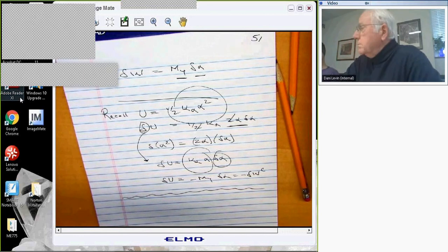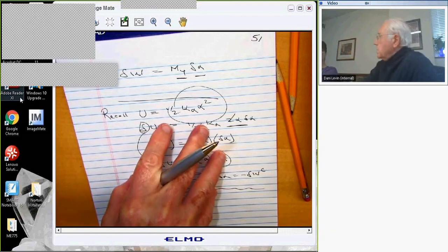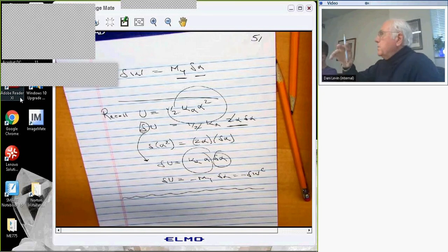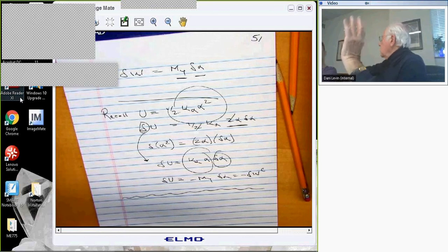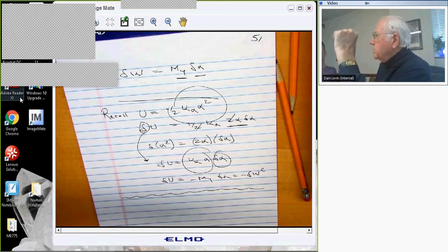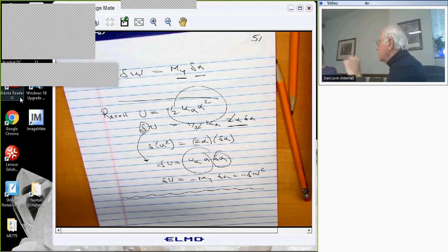I hope it's the way you like as well. While we're here, and anticipating what we'll do later on, although this is not really static, why don't we try to compute the virtual work done by a damping force? What we've done now is compute the virtual work due to this elastic spring. But whatever mysterious physical source is giving rise to damping in the structure, it could be because the structure, when it moves, rubs against something and there's some friction. Who knows? It could be some internal damping in the material itself, which is usually not very important in aeroelasticity, although there are people who spend their careers thinking about that. But it's largely a waste of time for most practical engineering, not necessarily for nanoscale devices, but for a real airplane.